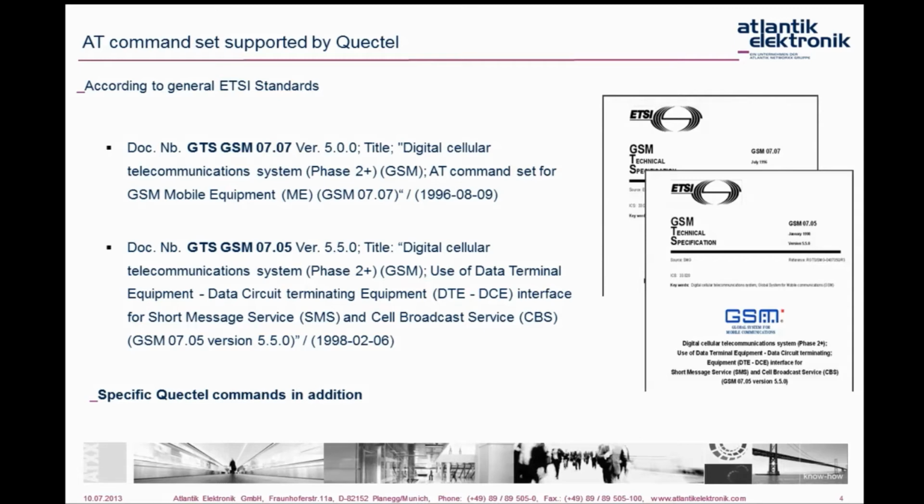While estimating the complexity of the implementation of Quectel modules, it is important to know what I need to implement, what is the AT command set I have at disposal, or what changes I need to do, what I need to adapt in order to implement it in my application. Good news when using a Quectel module is you need to change almost nothing in your software. It is because it is all much standardized.